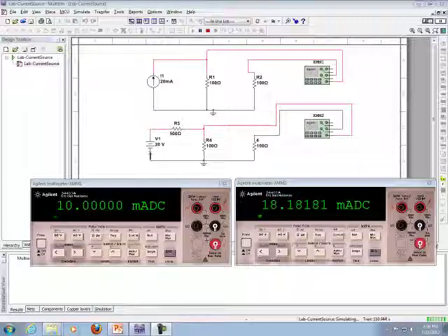So that means what is acting as the constant current source is the fact, or in other words, we're making use of the fact that the E3631A power supply has a constant current functionality. So we're going to set the limit on the power supply to be 20 milliamps. So as the current starts rising from the power supply, it does not go up to 40 milliamps. It goes up and stops at 20 mil.